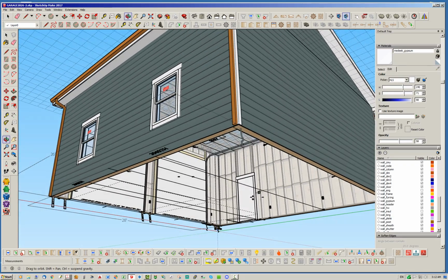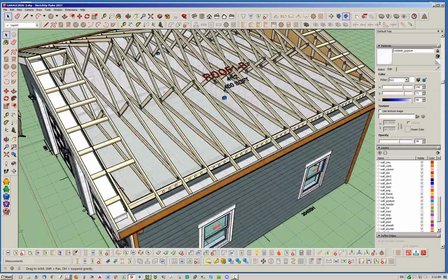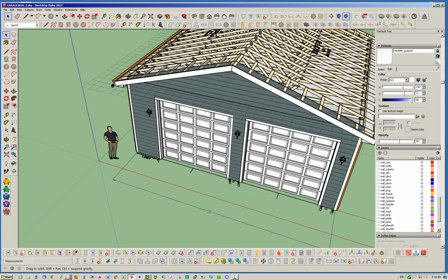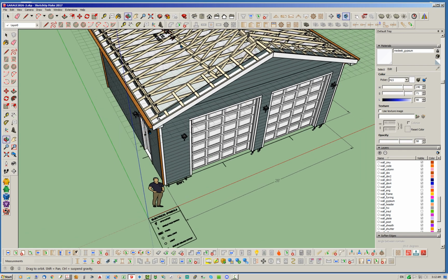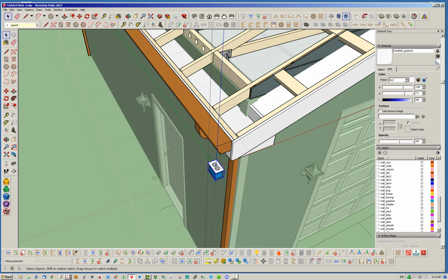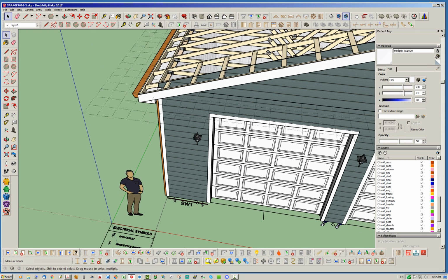Anyways, long story short, you'll notice now that the outlet symbols and the light symbols are positioned on the floor, as well as all the other light symbols. And then just as one final step, if you like, you can create what's called an electrical legend. You just click this little legend button, and it figures out everything that's in the, oh, there's our extraneous light. We can delete that. There were a couple of them created there. Well, that's where they were getting dropped, I guess.